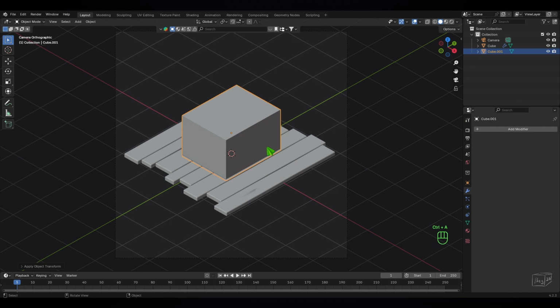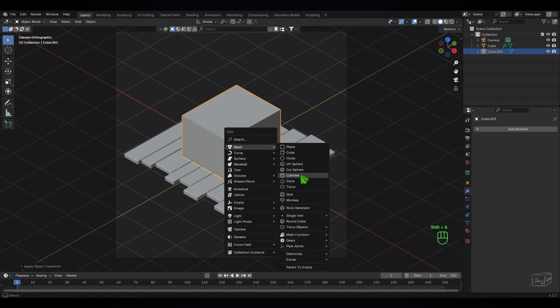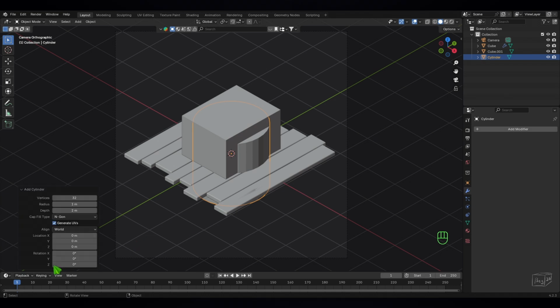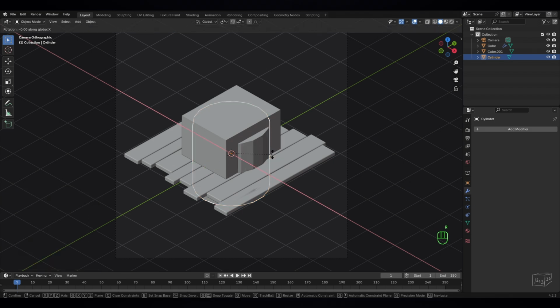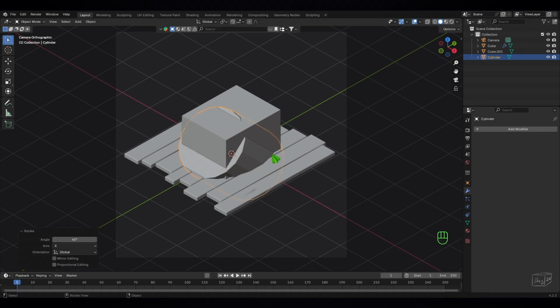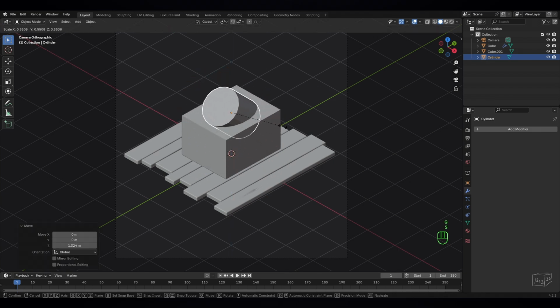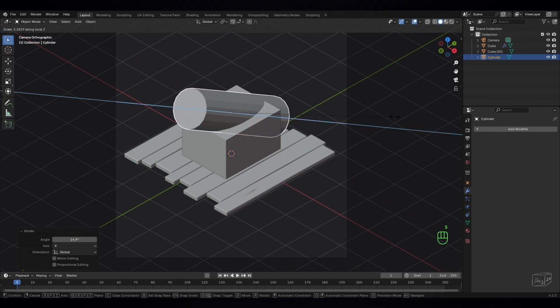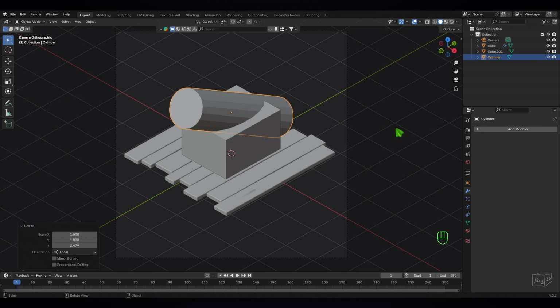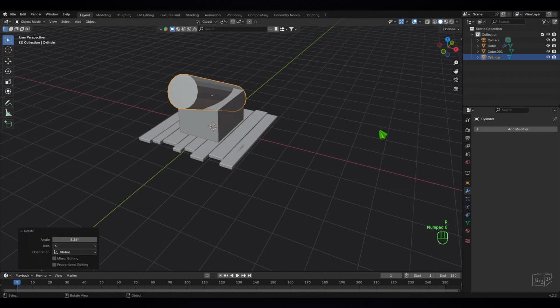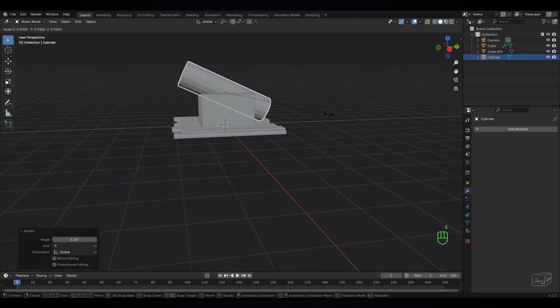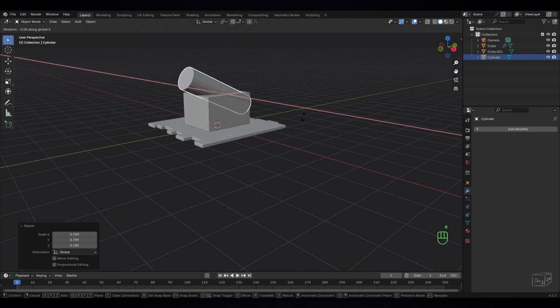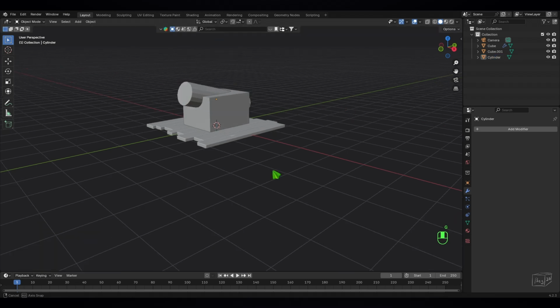And the next thing, we need a cylinder, and just open this up. This is too many vertices, 32 is too much. Let's put it at 18 vertices, rotate it 45 degrees, move it up and scale it down. Let's rotate a bit and scale it up on the local z-axis, something like this. I think let's go up. This is just blocking out how our things look.